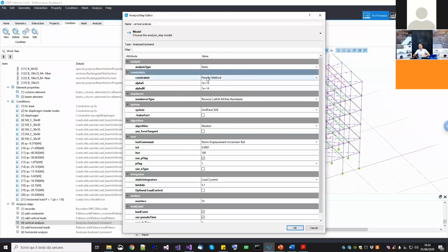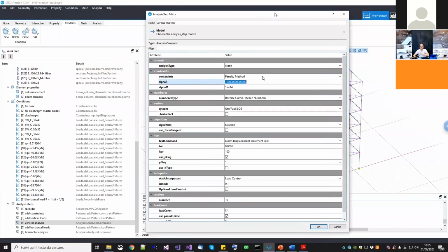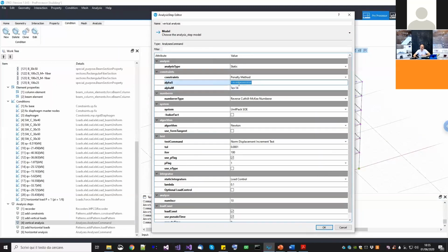Now, transformation works fine, but it is not general enough because when you have many constraints, like when we are going to create the beam column joints, the transformation method may not work because some constraints may overlap, okay? So it's easier to use the penalty method. Now, the penalty method has a problem. It's actually very easy when you understand it, but you have to choose the penalty parameter. Now, by default in STKO, we choose 1 to the power of 18. But then it is problem dependent. So how do you choose it?